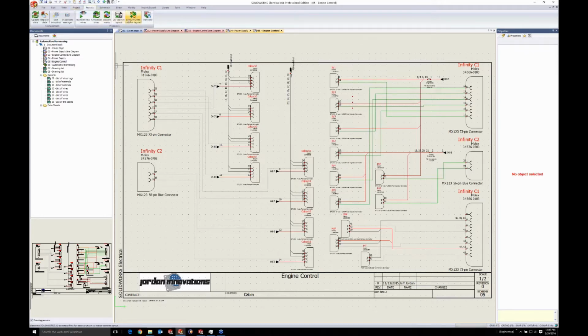I then, in SolidWorks Electrical, create what's called a SolidWorks cabinet layout. They call it a cabinet layout. Basically, I'm creating a 3D assembly for this model. Workflow-wise, I don't want to recreate the entire mechanical assembly of whatever I'm using. I just want to use it to route. So generally I will insert my previous top level, or if I'm only routing using a subassembly, I will insert that subassembly into my new SolidWorks Electrical created assembly. I'll show a little bit about that.